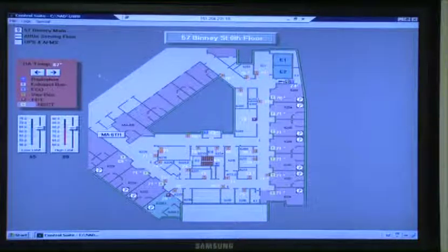But from a graphical and a whole flow standpoint, we've got to make it the way they're saying it's going to operate. So make it pink. It's an HSCT suite, but you've got to call it out as a protective environment room, because that's how it's labeled on the plans. These are positive pressured rooms, and this is considered a protective environment. You know what I mean? So full boat graphic, call it not isolation, but protective environment, because it's not a negative isolation room. And we'll go from there, all right?